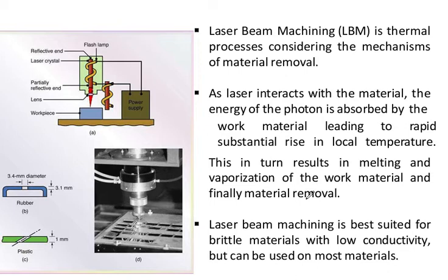What we know is that laser beam machining, or more broadly laser material processing, basically deals with machining and material removal processing like heat treatment, alloying, cladding, sheet metal bending, etc. Such processing is carried out utilizing the energy of the coherent photons of the laser beam, which is mostly converted into thermal energy upon interaction with most materials.